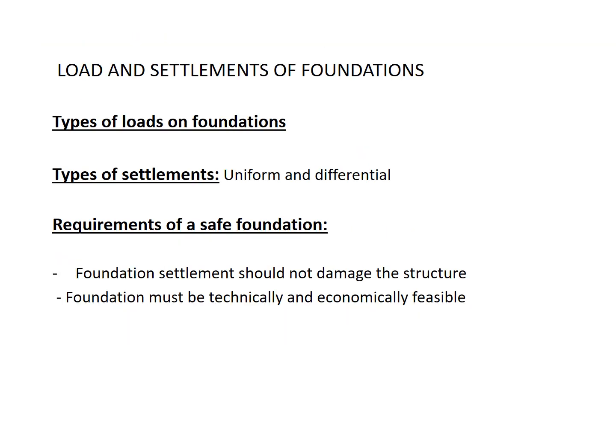So, loads and settlements of foundations. Well, the types of loads on foundations, we can break that down into dead loads and live loads, wind loads, inclined thrusts and uplift, the water table, and earthquake forces. And types of settlements, well, there are two types, uniform and differential. Differential settlement must be minimized and depends on the soil condition and distribution of loads on the columns supporting the